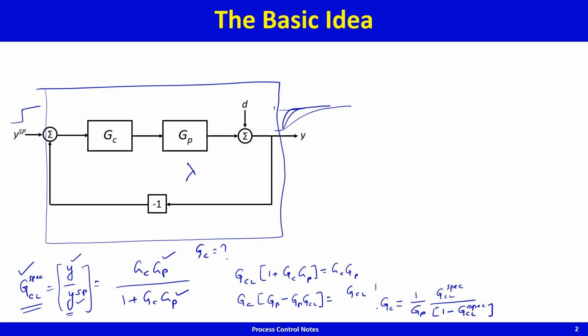So this is how you back calculate what the controller equation should be for a specified closed loop transfer function.